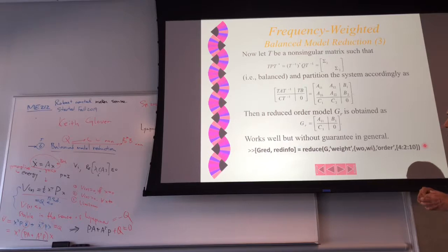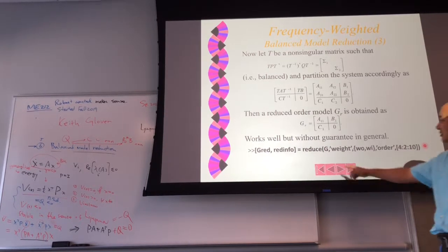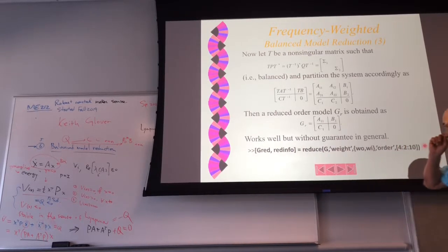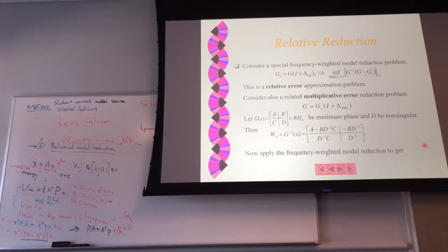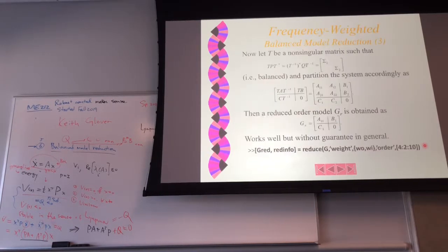However, in a more general weighted balanced realization, you can use the command reduce with those weights. So that is model reduction in the frequency domain with weighted filtering, and we have a ready command to do the job.